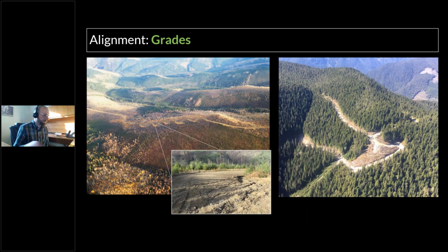And in this case, instead of that water naturally falling away from the ridge, it gets trapped on the roadway. There's poor drainage structures and it's dished together. So a little bit of water that starts at the top of that series of curves doesn't have an opportunity to leave the road, and it ends up creating a lot of water on the road, which washes away your surfacing and puts that material someplace where you don't want it.